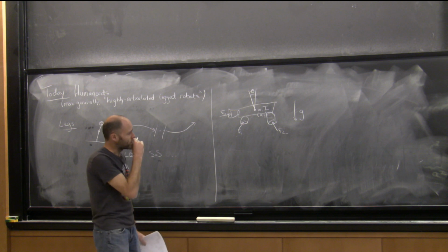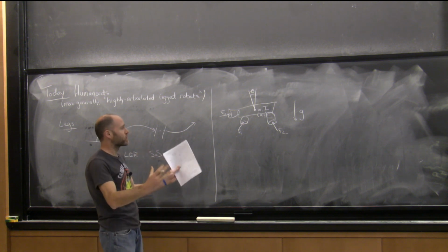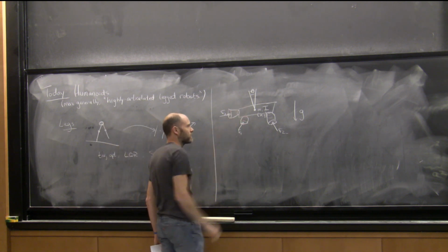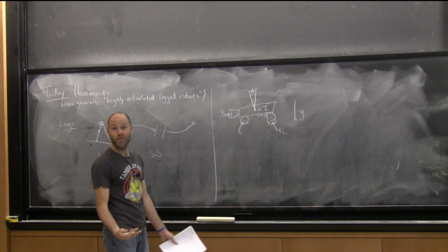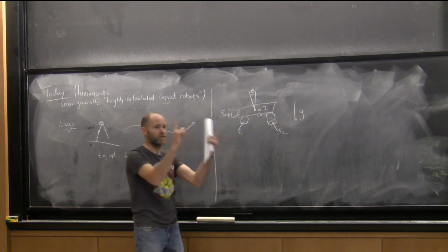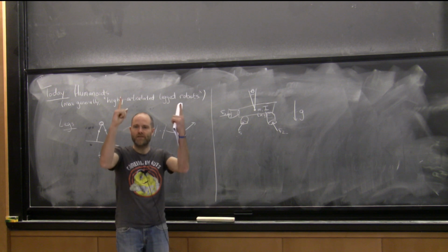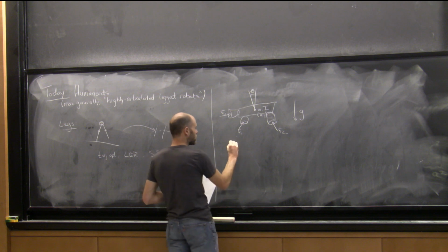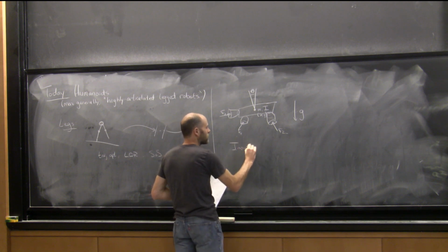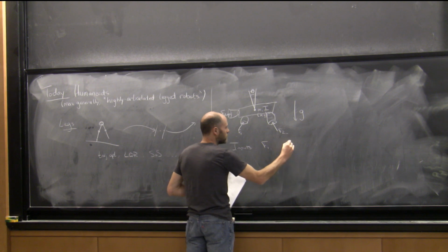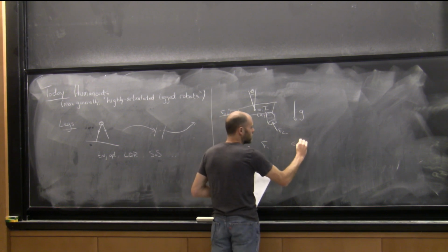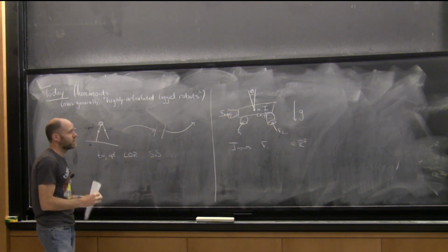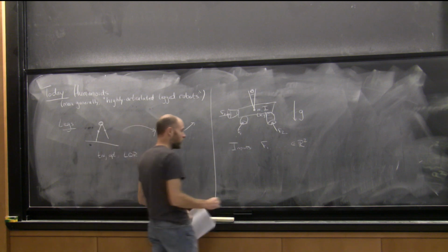possibly vectoring. So this is a lot like the planar quadrotor that I wrote down before, but if I allow vectoring here, then I have an even simpler problem than the planar quadrotor, where the quadrotor was restricted to produce thrust along the axis of the rotors. This one, I'll say it can produce forces in either direction. So if my inputs are force 1, however many I have, and they live in R2 because I'm in the plane here, so I get to control x and y of the force, then my dynamics